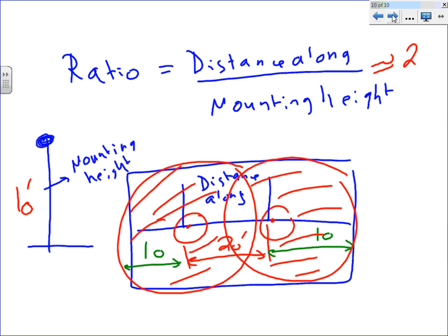I'm looking at page 47, Mr. Erbab, and there are some rules of thumb. They're telling you if you use a fixture like this with 4 lamps, and they're not saying anything about the lumens, the lumens are probably 3,000 or so, and that one 4-lamp fixture can cover up to 47 square feet if you are looking for 75 foot-candles. Again, rule of thumb, it really varies.